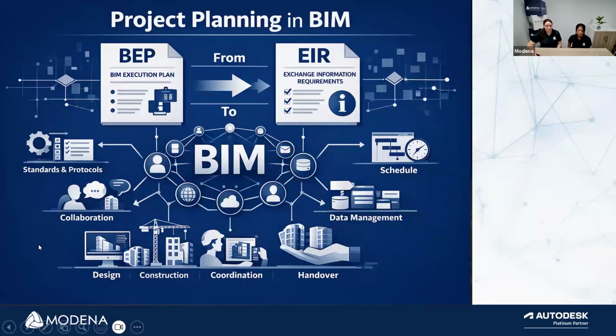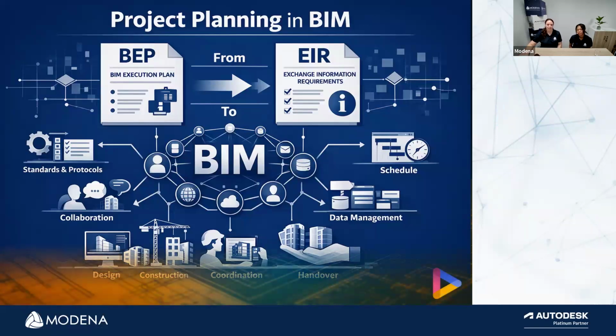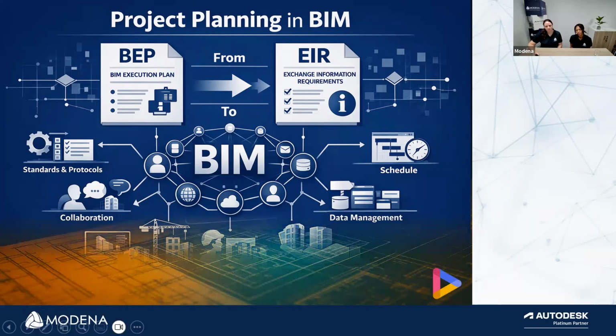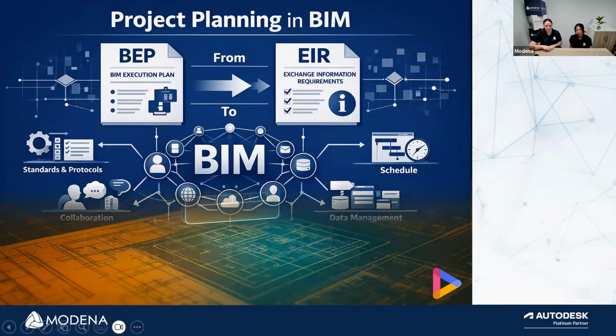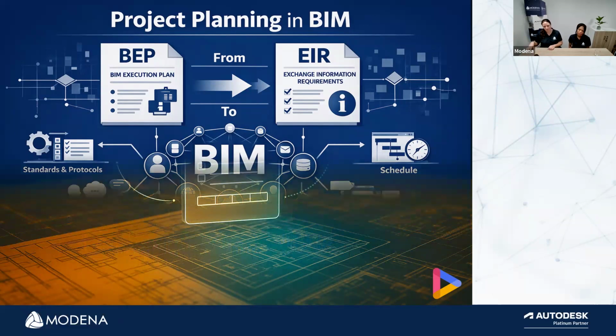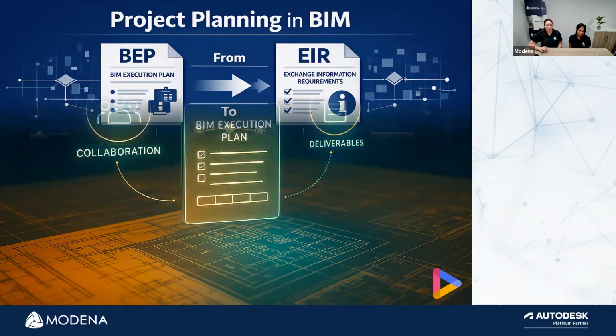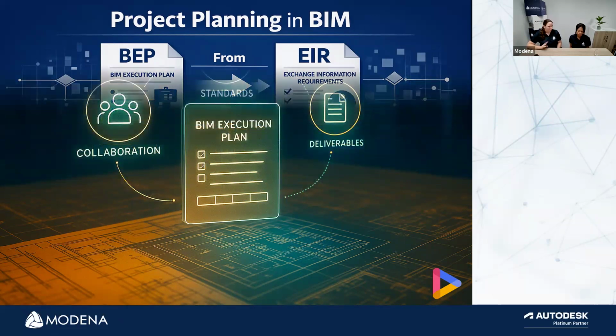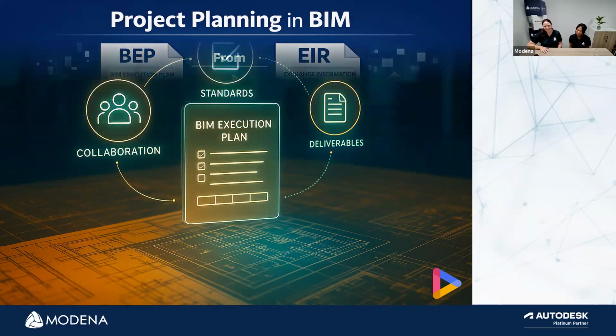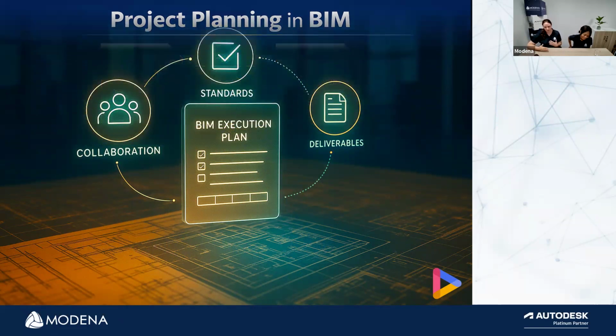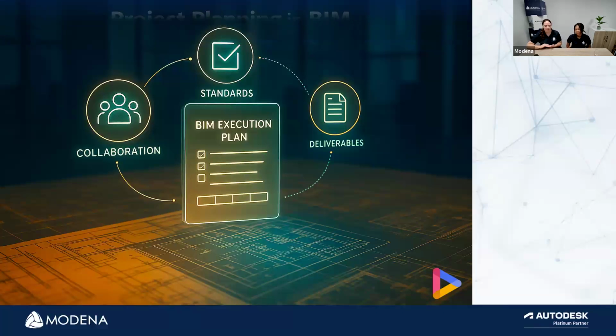So how do we visualize within Revit? In Revit, we're using parameters to associate all this data to the relevant components and elements in the project model. These parameters ensure that the data stays associated to that component even when it's exported into different file formats or as it moves through different phases of the design. These formats can include IFC, NWC, Excel, and quite a few others that are coming through nowadays, because those can all form models, as I spoke about at the beginning. It may be required at different phases to export the different file types so that the data can be read and used in different programs or to inform documentation needed for the build to continue.